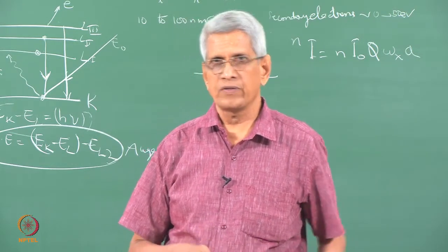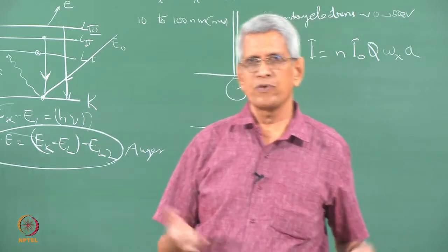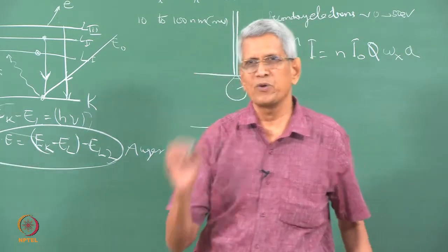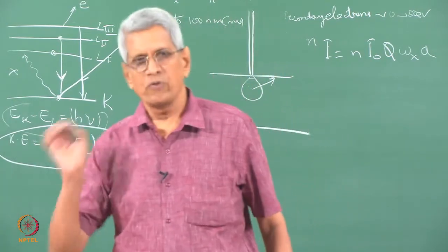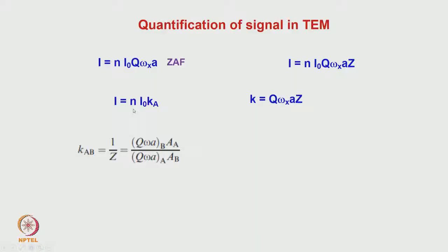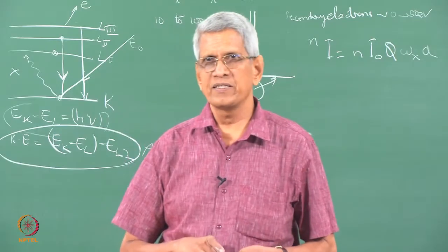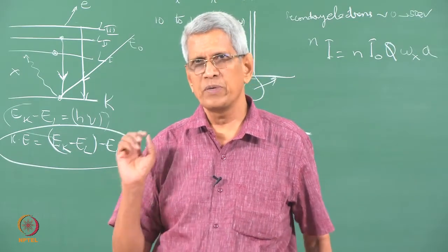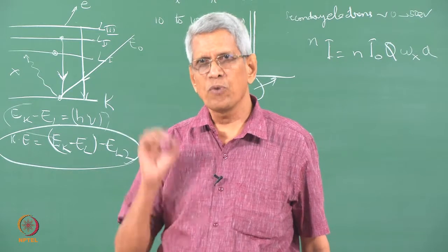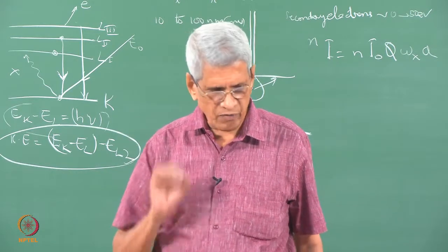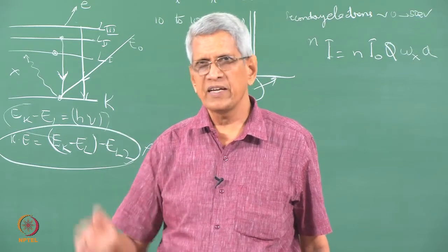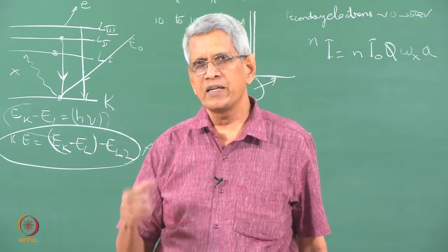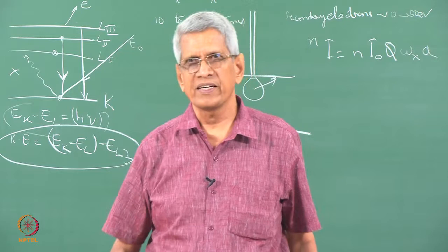That means that if a sample contains 10 elements, we should have a pure elemental standard for all of them, and we have to maintain an identical current to measure this intensity, which is quite tedious. So, most of the time, because of this, we use a standardless technique, which is essentially nothing but the relative concentration.